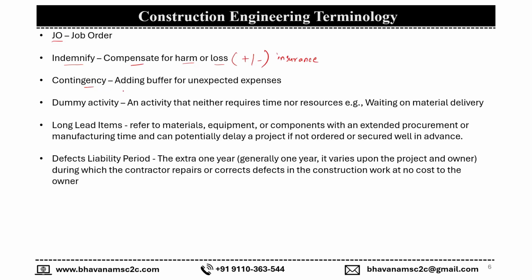And contingency is adding a buffer for unexpected expenses. It comes under the concept of estimation. A QS is well aware of this word. Whatever project you quote or bid, you put on some contingency charges worth 10 to 15 percent for every project.